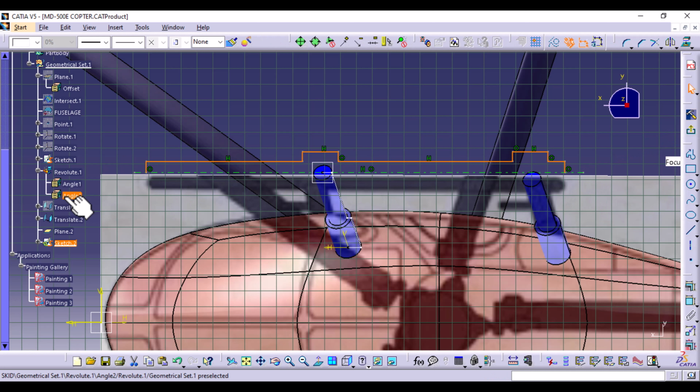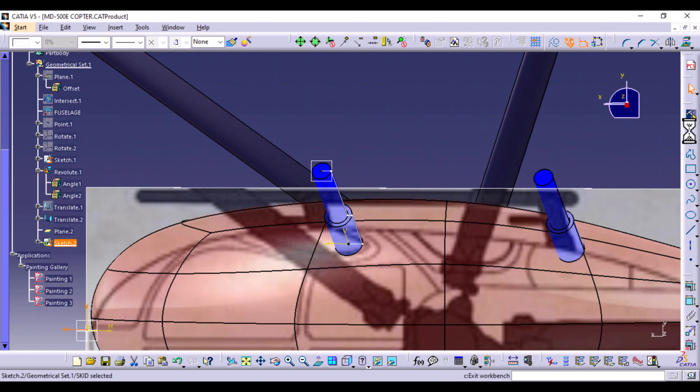So I know the blueprint is showing that this stand is at this point and we are creating it here. So we're just using this reference, the length one, because we didn't enter the width dimension. We only entered the length. So for this top profile, just use the length, okay? Then exit. If you wish, you can make this line and this line equal length. It doesn't really matter. Exit.